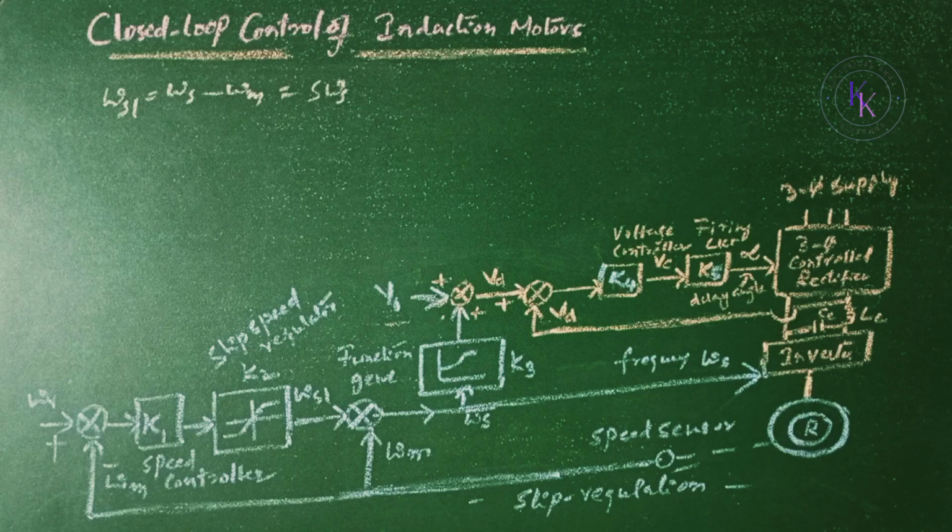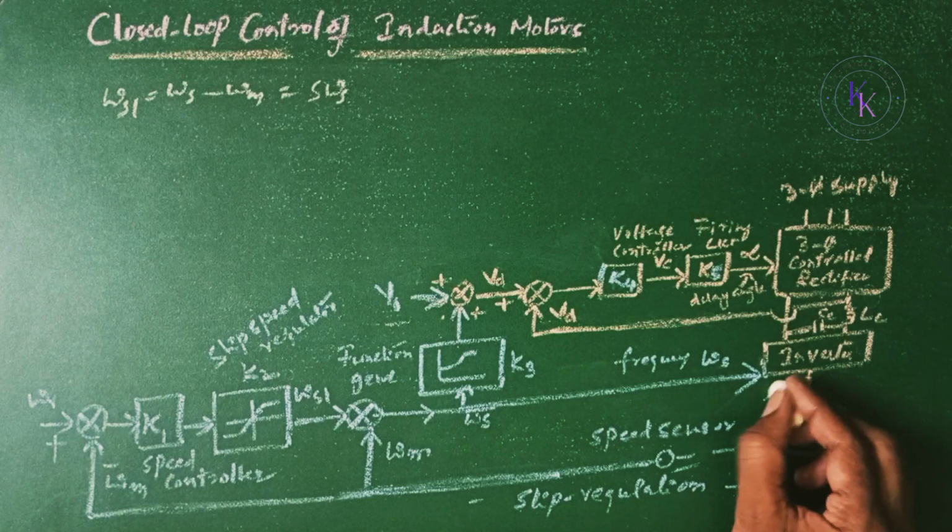For a step change in the speed command, the motor accelerates or decelerates within the torque limit to the steady state slip value corresponding to the load torque. This arrangement controls the torque indirectly within the speed control loop and does not require the current sensor; it is absent here.